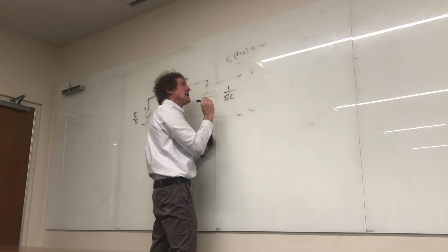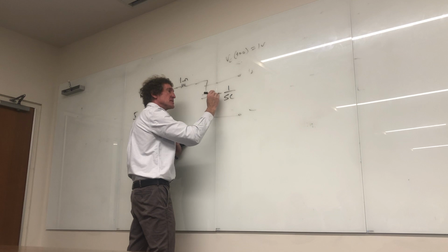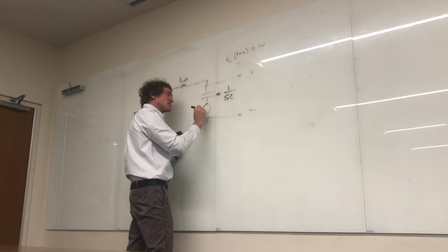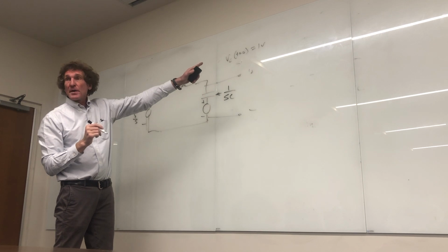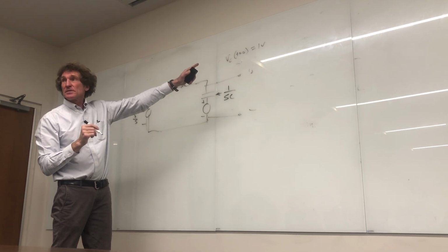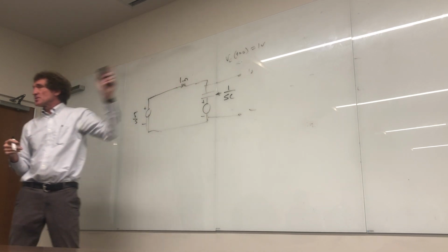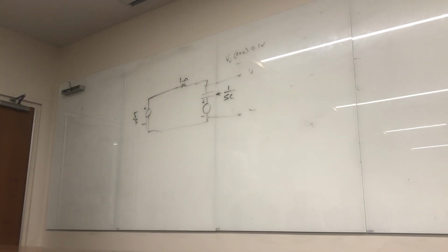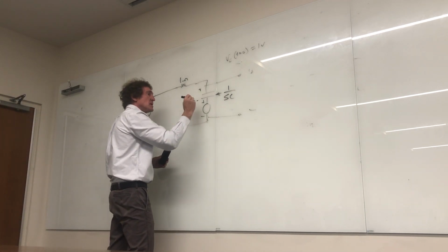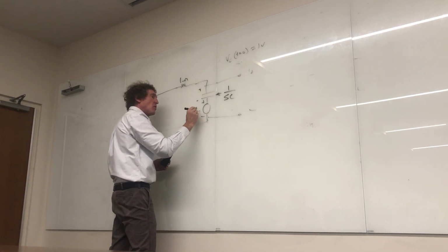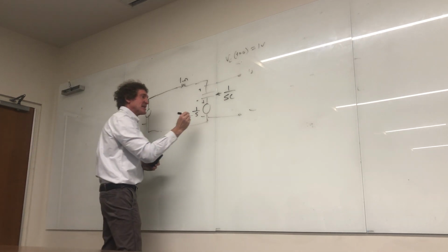That's the impedance, think impedance, but then there's a voltage source, plus to minus what? 1 over S, correct class? Do y'all remember I just put that up there? If you don't, look at your notes. It's going to transform as V naught over S, and the polarity is the same as the polarity here. So this is just 1 over S, because the voltage was 1, correct class? But make sure you say this is a voltage.